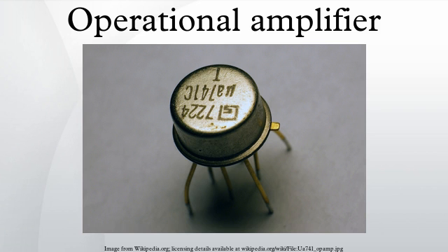Output amplifier. In the circuit involving Q16, the 4.5k resistor must be conducting about 100 µA, with the Q16 VBE roughly 700 mV. Then the VCB must be about 0.45 V and VCE about 1.0 V. Because the Q16 collector is driven by a current source and the Q16 emitter drives into the Q19 collector current sink, the Q16 transistor establishes a voltage difference between Q14 base and Q20 base of approximately 1 V, regardless of the common mode voltage of Q14/Q20 base. The standing current in Q14/Q20 will be a factor exp(100 mV/Vt), approximately 36 times smaller than the 1 mA quiescent current in the Class A portion of the op-amp.